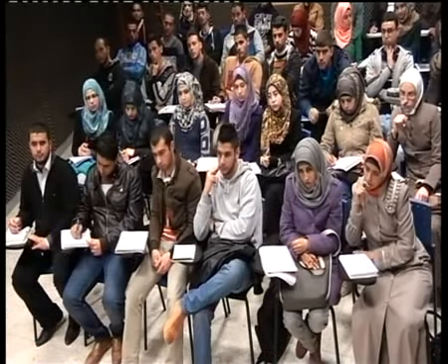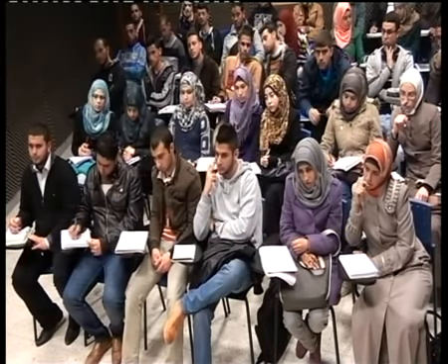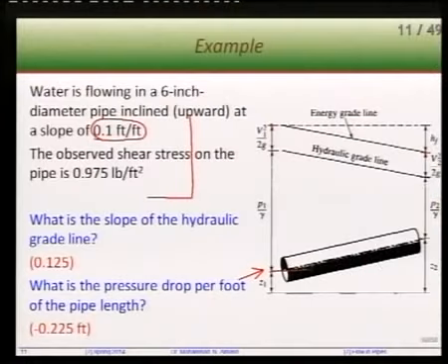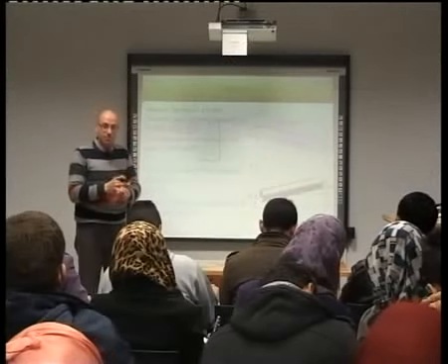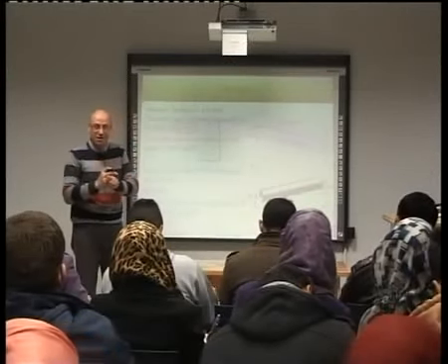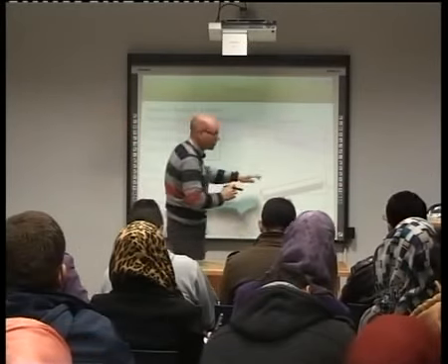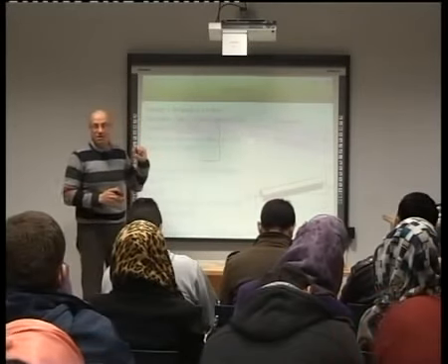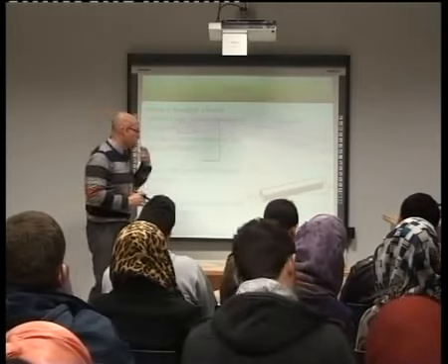Only, just because this is delta z. So to apply, now this is a different case from a previous case. This is still uniform, so you still can drop the v square over 2g, but here you can't really drop the change in elevation. So you must take it into consideration.